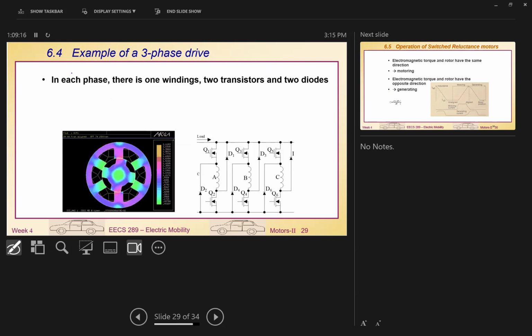You can also see that the motor inverter is quite different. Before, for the induction motor, we used two transistors for one phase, and here we're still using two transistors, but the two transistors are arranged in a different manner. These two ports are not joined together, but will be used to connect to one winding. So when you energize them, when we turn on these two transistors, the current will feed back and return to the battery. So it's quite special.